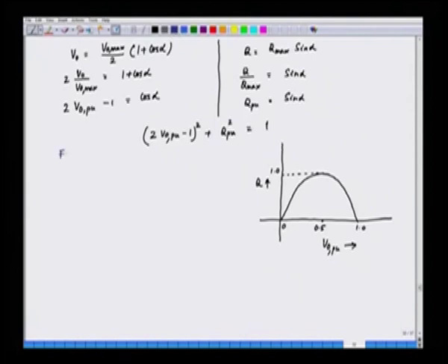So, this we can see here that for two stage converters, we have, let us say, V naught 1. If you start with V naught 1, so V naught 1 here is equal to V naught max by 4, because this is half the output voltage, into 1 plus cos alpha 1, let us say.